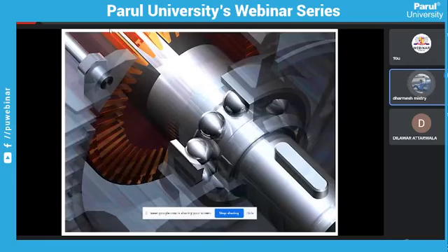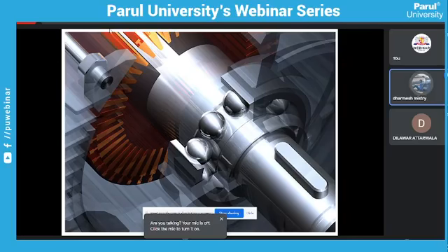This is just an image showing the bearings, the bearing walls, the rotor, and the case, where you can see that due to different failures, for example if the bearing oil has got completed or is not there, or the bearing is getting rusted, or the bearing balls are getting damaged, or the rotor is having some issues, or there is some misalignment, the vibration starts increasing.